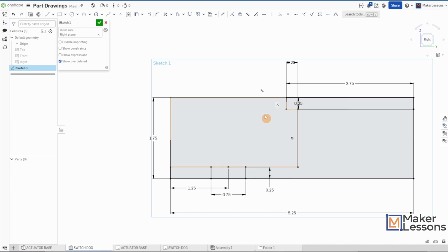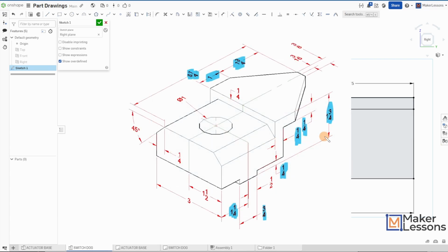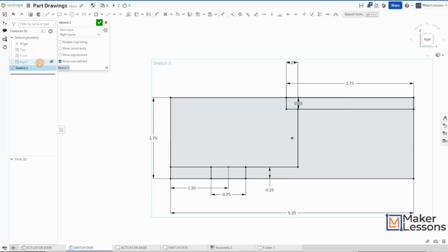And the last thing is what's going on up here. We need a line going all the way across, I believe. Let's double check that. We'll jump back over here, look at what we're doing. I got this front. I just need to know what's going on in the back here, and this point going back. And over here it's 1/4 inch, which is the same. So this thickness here, this point's actually aligned with that point. Doesn't look like it, but that's because we're looking at an ISO view, and that's why we don't give technical drawings in ISO view. So that actually just means that I have a line going from there to there.